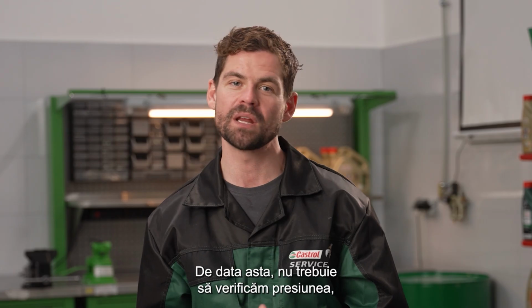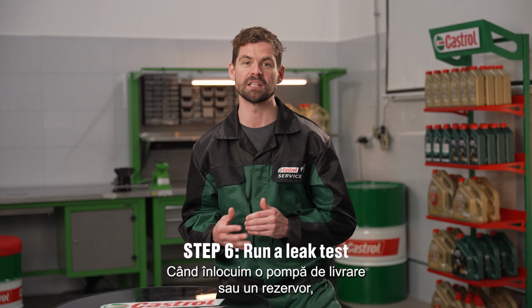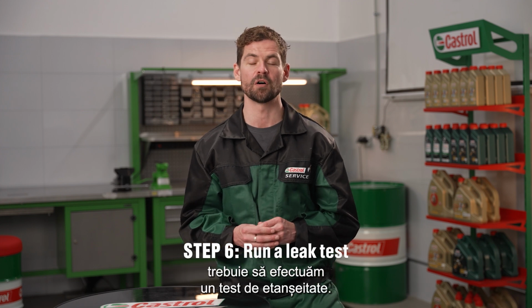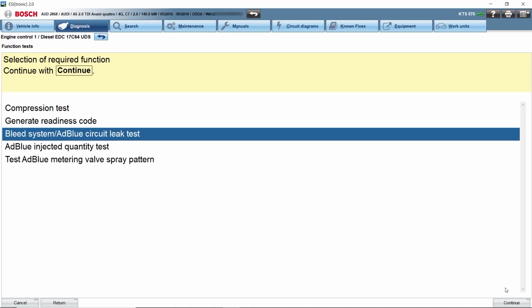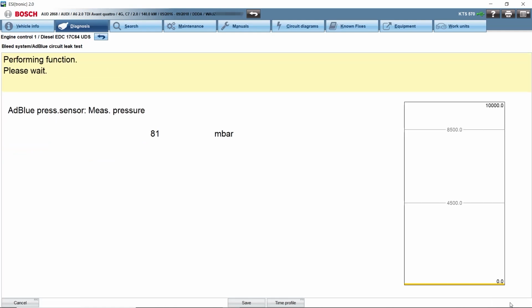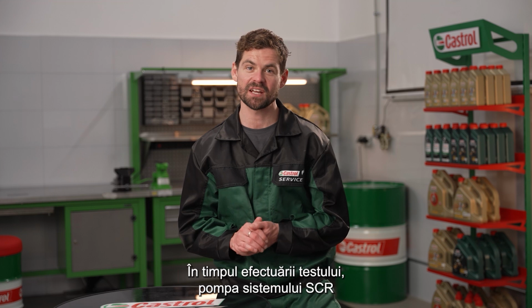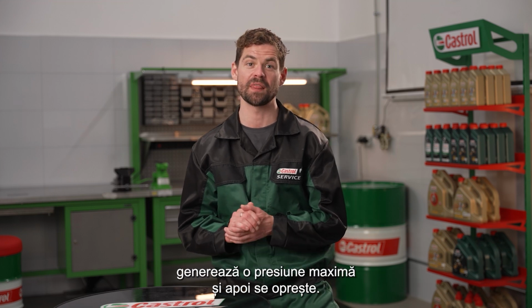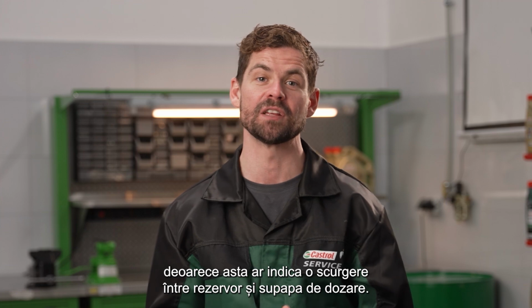This time, we don't need to check the pressure since we've already seen it was working properly in our last test. When replacing a delivery pump or tank, we first need to perform a leak test. This is done using the bleed system AdBlue circuit leak test function. As you can see, the results are all good. While performing the leak test, the SCR system pump generates maximum pressure and then shuts off. Our job is to make sure that the set pressure value in the system doesn't drop, because that would indicate a leak between the tank and the dosing valve.